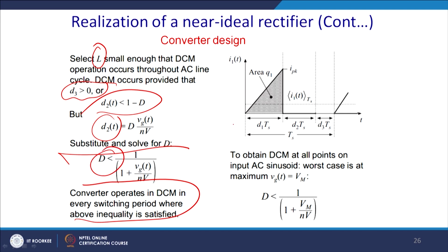So, you can see that when the switch is on, the current will peak up, which is a problem of EMI EMC. This dotted line is basically the average current. In this region the switch will be on, and the inductor will be building up the current through it.